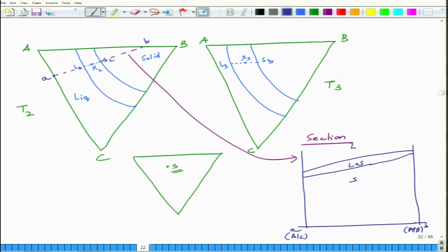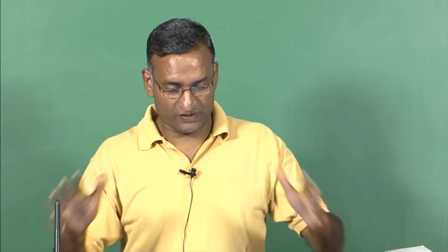So what we have done in this lecture is we have just looked at some graphical description of a ternary phase diagram consisting of two phases. So A and B and C are completely miscible in both solid and liquid state. We have seen how one can determine the phase compositions and phase fractions by drawing the tie line, and you can visualize the solidification phase changes by drawing the isothermal sections and drawing isopleths. So in the two other ternary systems, and before we finish this discussion, thank you.